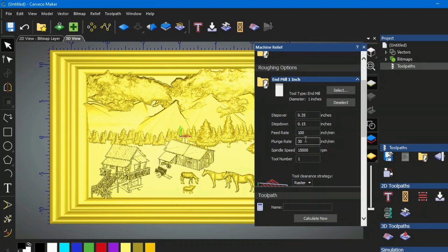This is only a rough-in, but what I have found is if you have high feed rates, of which these are pretty fair, you need to probably take the RPM up just to increase the torque of the spindle quite a bit.